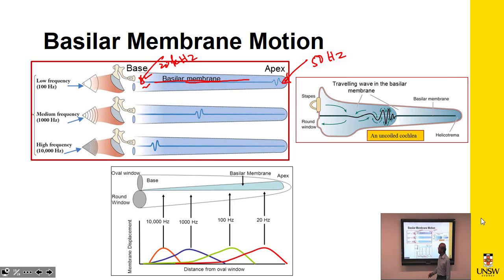So we explain to them, if you give a frequency of about 1 kilohertz, the signal travels, and at the position where it's 1 kilohertz, it vibrates, and then the fluid does not travel. That's shown here as well. You can see the traveling wave of the membrane. When this is vibrating at 1 kilohertz, the traveling wave travels and makes a resonance at that point, and then the wave does not travel at all. That means later on, the pressure difference here is zero. They need to demonstrate that in a picture once they have done the model.